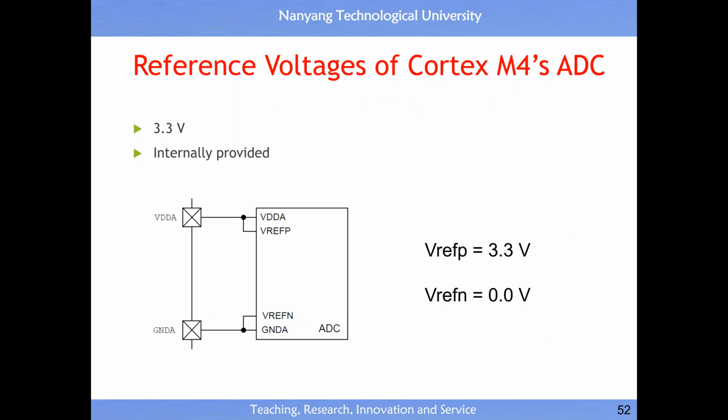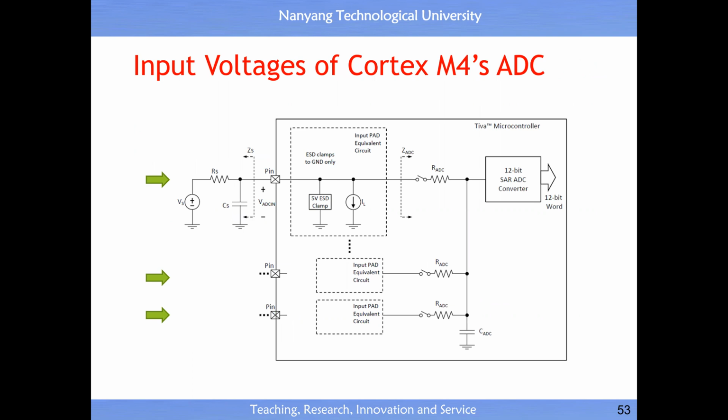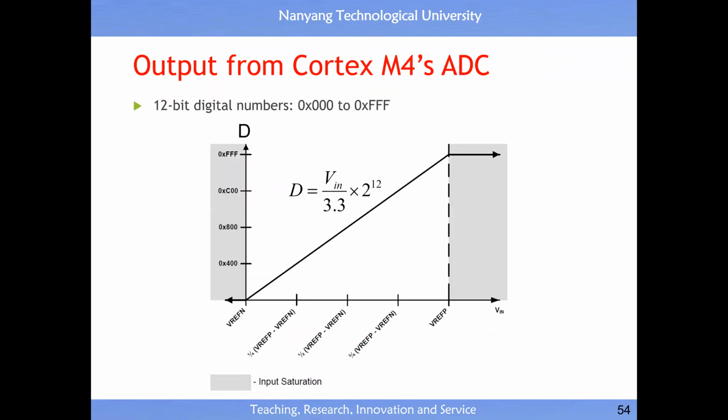Okay, the input range tells you the input to this microcontroller. If you use it as a sensor, it must be voltage, right? Within this range, 0 to 3.3, okay? And this shows you inside, the hardware is actually very robust because it will do some filtering. So even in a noisy environment, if it's not a lot of noise, this is also very reliable, right? Just for you to know this.